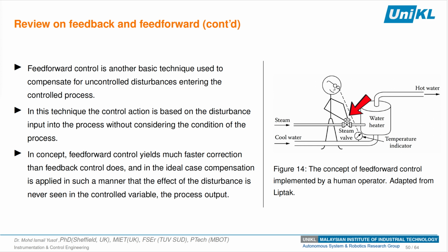most process control applications. In many cases, disturbances cannot be accurately measured, and therefore pure feed-forward cannot be used. The main limitation of feed-forward is due to our inability to prepare perfect process models or to make perfectly accurate measurements. Because of these limitations, pure feed-forward would accumulate the errors in its model and would eventually self-destruct. The main limitations of feedback control are that feedback cannot anticipate upsets but can only respond to them after the upsets have occurred, and that it makes its correction in an oscillating, cycling manner.